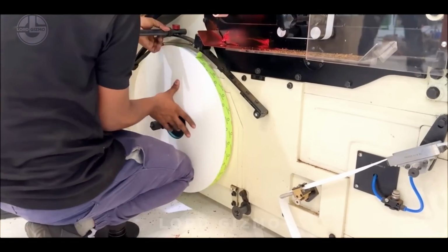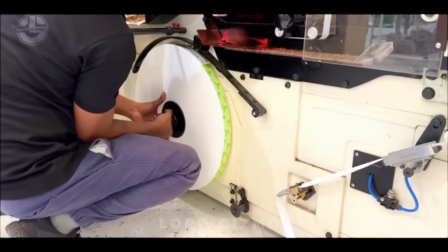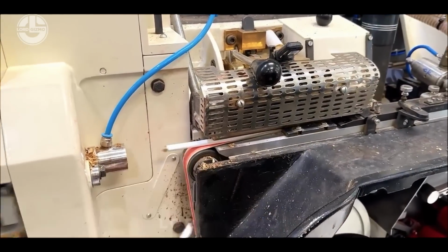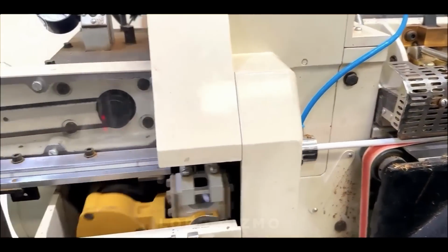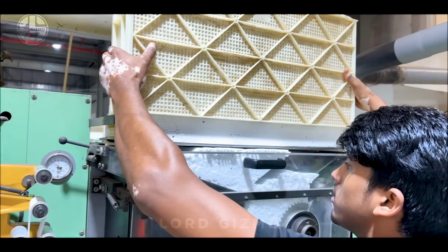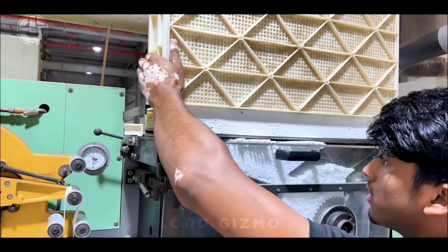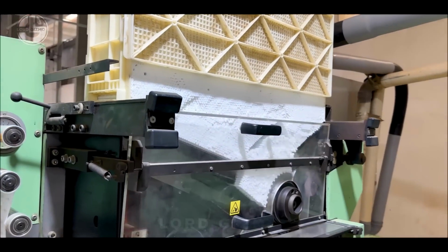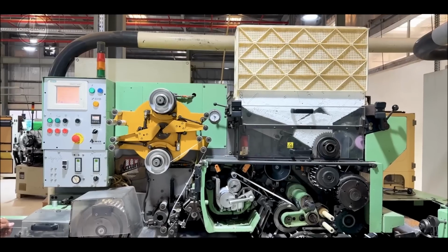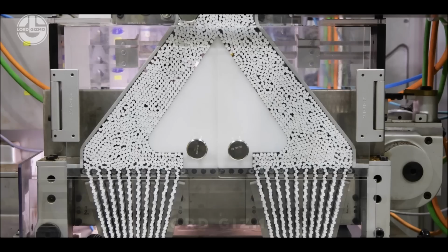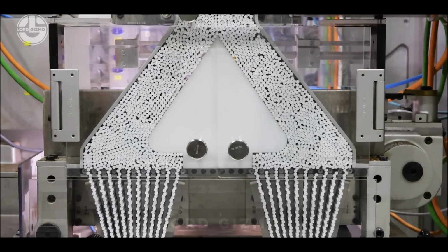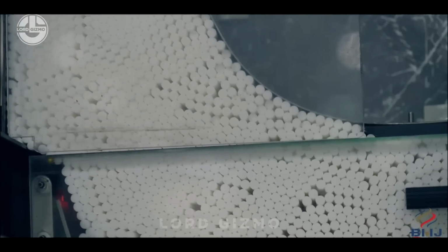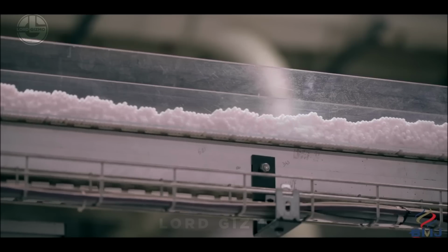To produce the rod, a spool of cigarette paper up to 7,000 meters long is unrolled. The cigarette paper is then wrapped around the tobacco, forming the rod. Next, filters are inserted into the prepared rods. These filters are primarily composed of synthetic materials, with the most common being cellulose acetate fibers, a type of plastic derived from plant sources. This material is created through the esterification of bleached cotton or wood pulp with acetic acid, resulting in a fiber that can be spun into bundles known as filter tow.